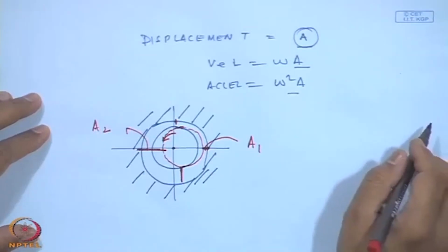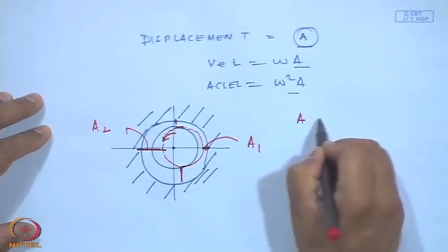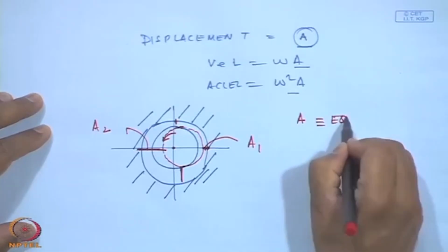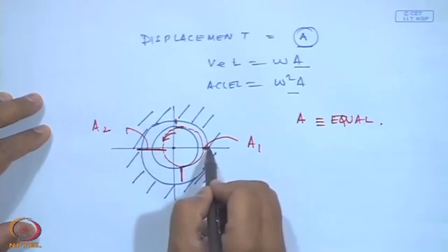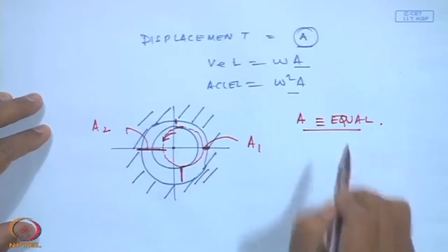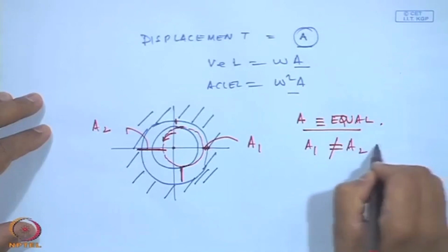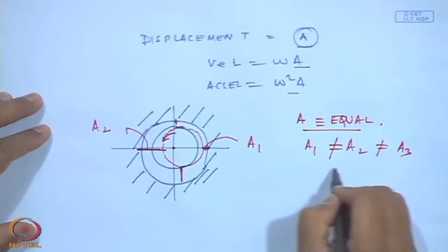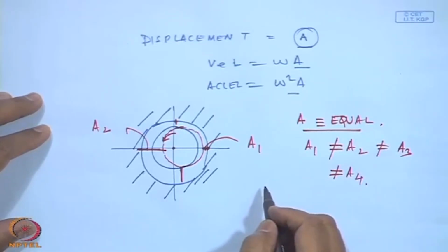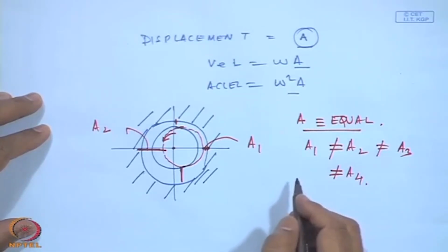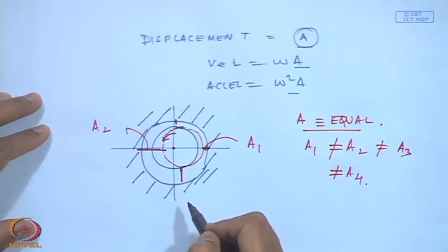For the shaft to be uniformly or concentric to the center, all these A's should be equal if you measure in the four quadrants or four directions, at 90 degrees to each other. But if you will see A1 is not equal to A2, is not equal to A3, etc., then we know there is some problem, because of eccentricity.